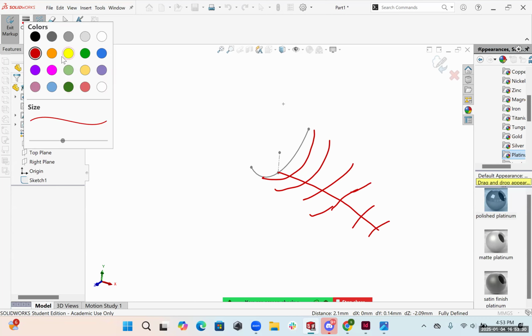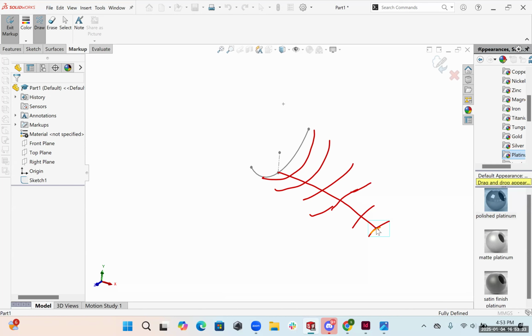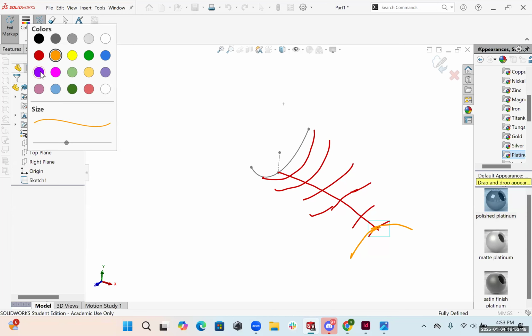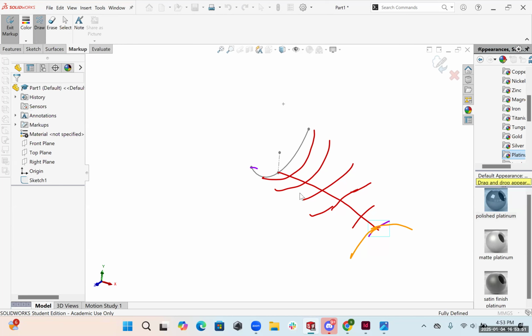We will come in and add another curve down here so we can control this transition going downward for the tail. And then afterwards, we're going to come in and add a connecting curve, again controlling all of these together. So you'll learn how to do boundaries with 2 curves, 3 curves, 4 curves, and later on 5 curves.